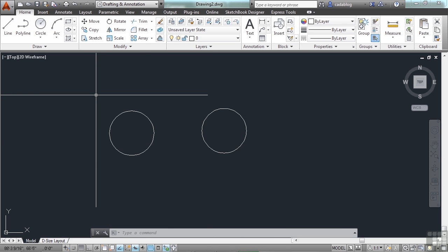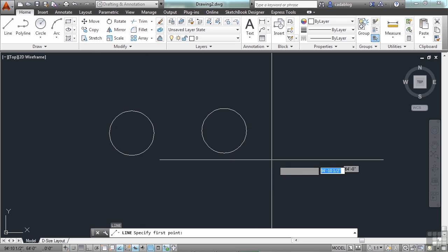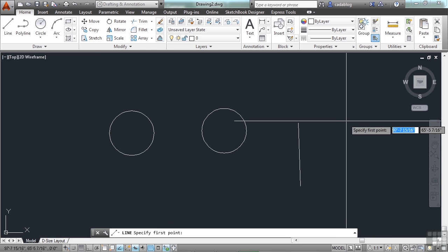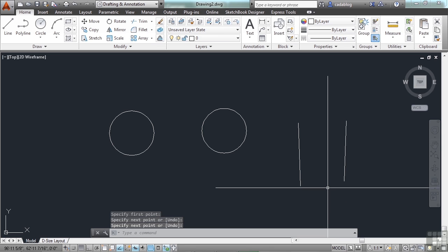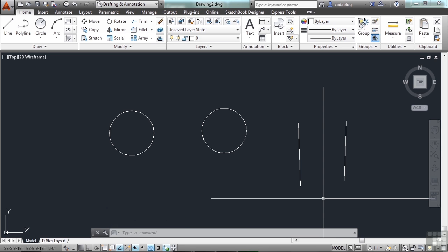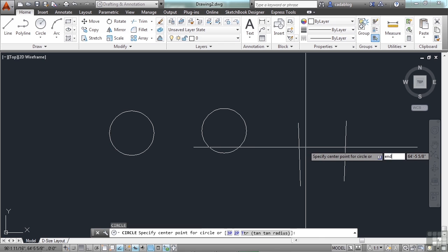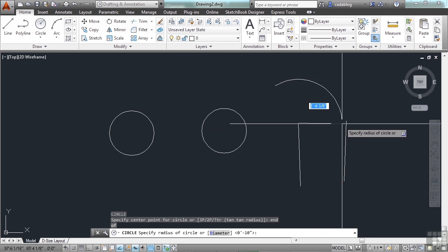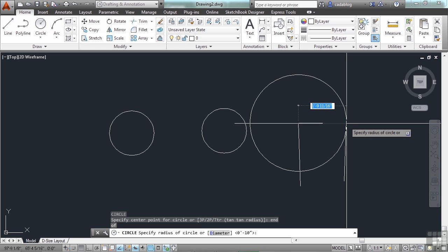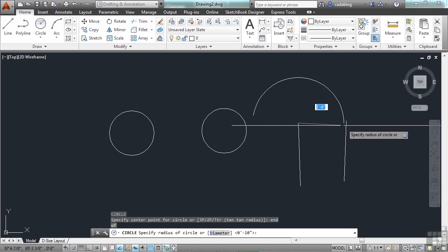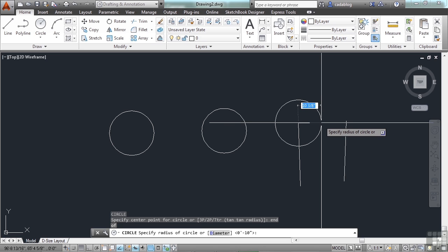That's important to know, because sometimes you have the diameter, and sometimes you have the radius. So, well, if I have one, I know what the other is. That's true, number-wise, but oftentimes when you're drawing in AutoCAD, for example, if I have this line and this line, and I need to draw a circle, what do I have? Do I have a radius or do I have a diameter? Well, that depends. If I start circle and I draw from this endpoint and I want to draw to this endpoint, I have a radius, not a diameter. That's true. But if I want the circle to come to the middle of these two lines, I will need the diameter. I'll show you the difference.